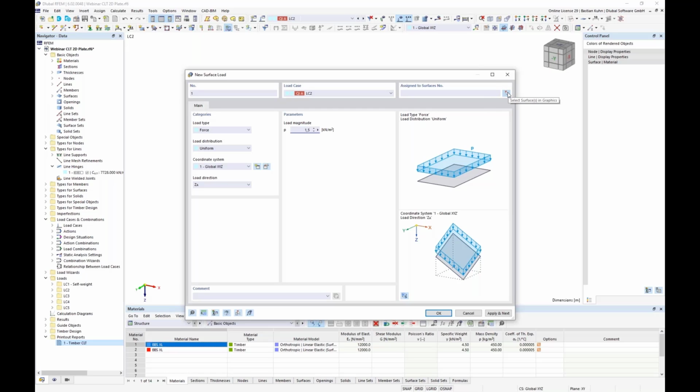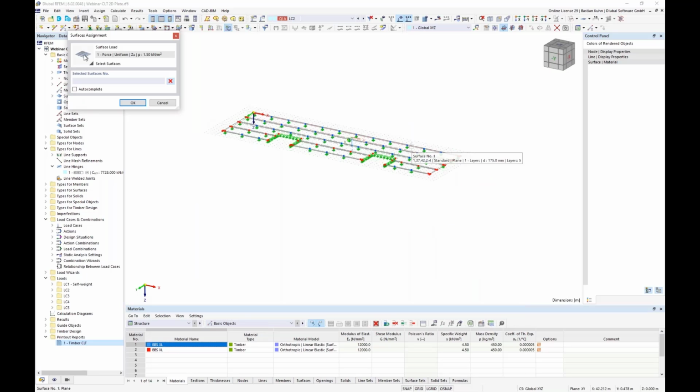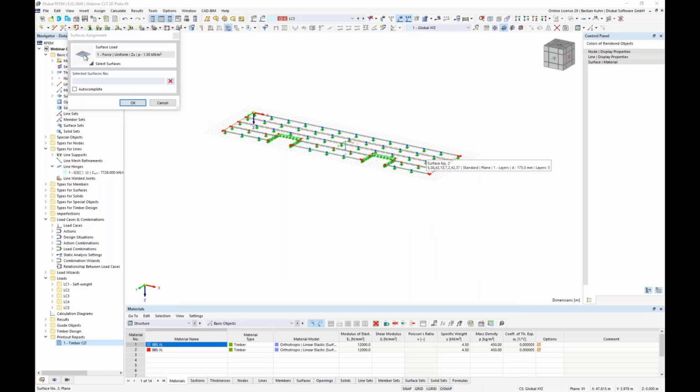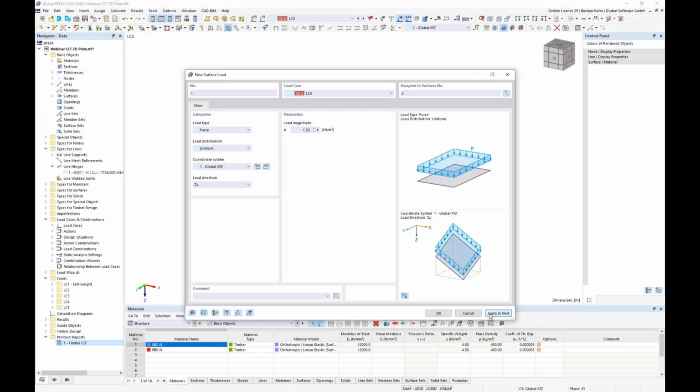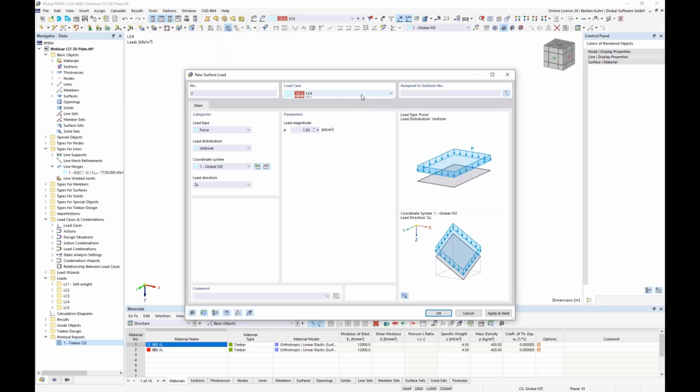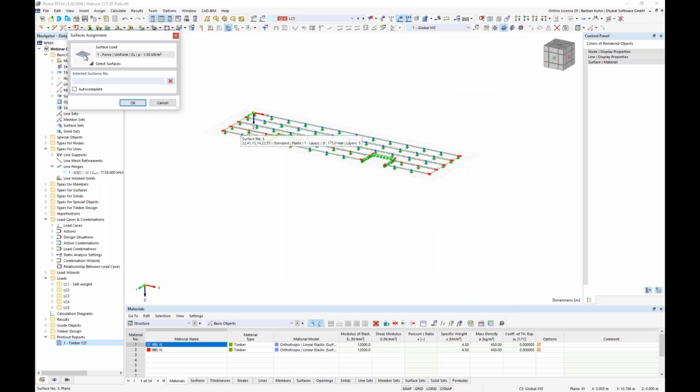But if you are new, you do not have to compare it. In RFEM5, you would have to define the surface on load case 2. Say, okay, leave the dialog, and then choose the second, or in this case, the third load case, assign it there, and so on. This is, as you see in here, also no longer necessary. All right. And last but not least, this one.